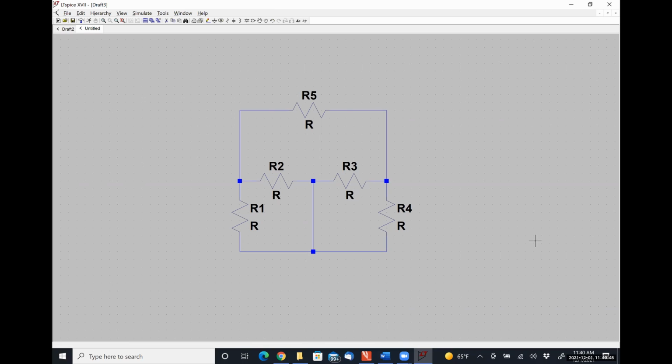Yes, a way to go back to the last thing that you had selected, so you don't have to re-click resistor, wire. Actually, you can press R on the keyboard for resistor, and L for inductor, and so on. I didn't even know that. So let's see what happens if I press the R key. Oh, I just get a resistor. I'll be damned. That's pretty easy.